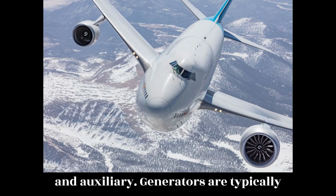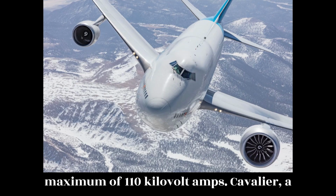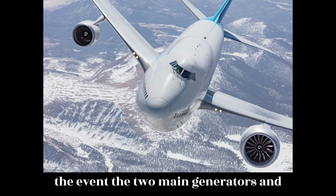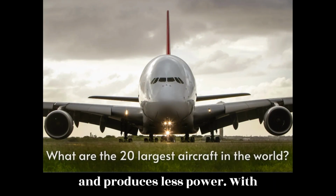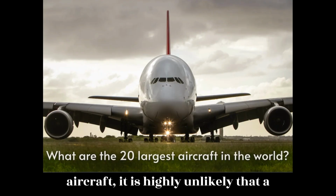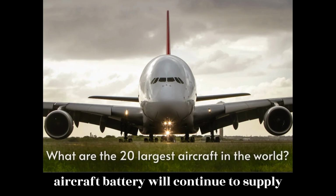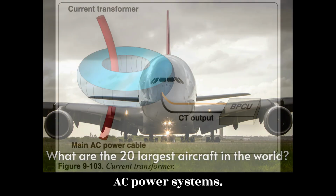The main and auxiliary generators are typically similar in output capacity and supply a maximum of 110 kVA. A fourth generator, driven by an emergency ram air turbine, is also available in the event the two main generators and one auxiliary generator fail. The emergency generator is typically smaller and produces less power. With four AC generators available on modern aircraft, it is highly unlikely that a complete power failure occurs. However, if all AC generators are lost, the aircraft battery will continue to supply DC electrical power to operate vital systems. AC power systems.